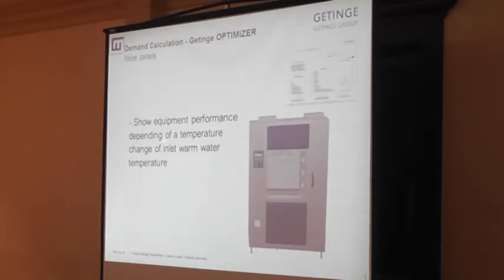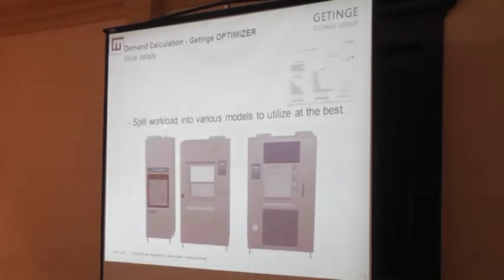And if we change the water temperature, that will also affect the program. Even the water temperature, we can simulate how much the machines differ if we lower or raise the water temperature. And we can split into different sizes of washer; it's even possible to split the loading. So we can even simulate what will happen if we have 3 different washer sizes. We can see how many machines of each are needed. It's not very common. It's more recommended to have the same washer.